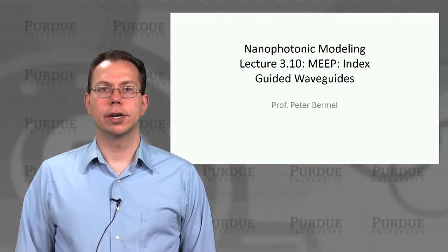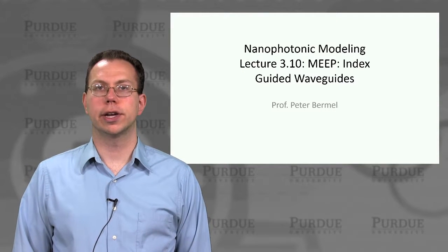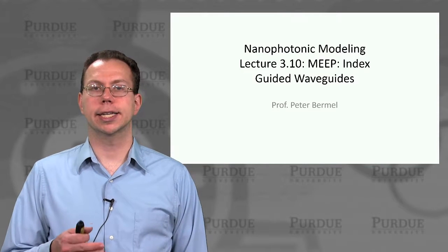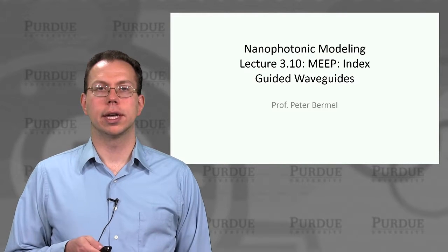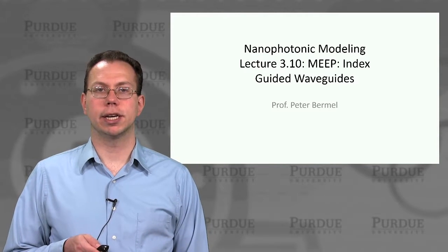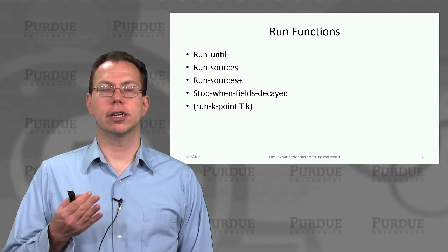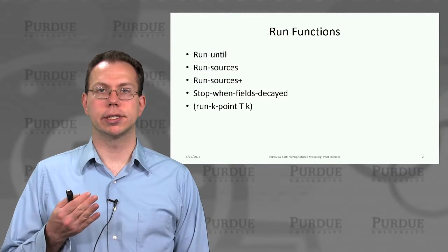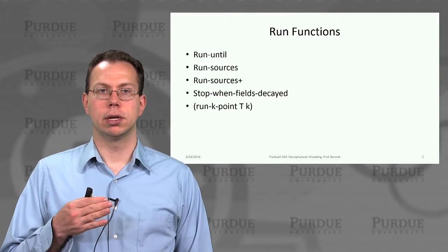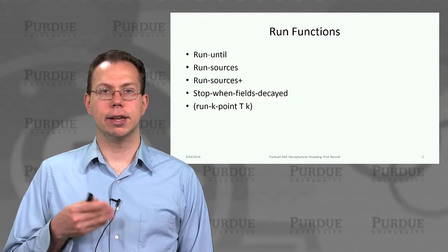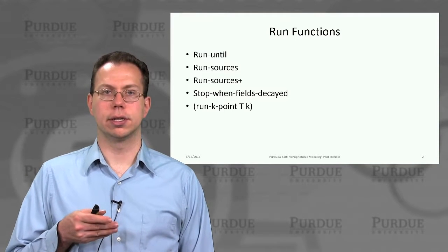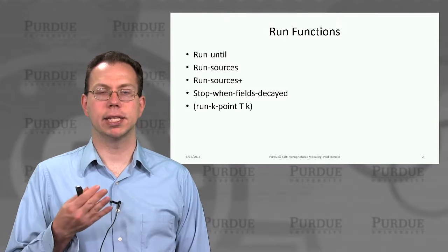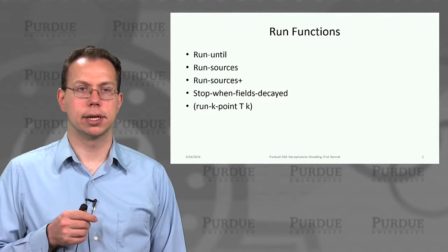Hey everyone, welcome to lecture 310. So now we're going to talk about index-guided waveguides in MEEP. The reason we're doing this is because we had already talked about the basic components and classes of MEEP. But in order to actually get any results, we have to run the calculation. And that means basically doing time stepping in our case.